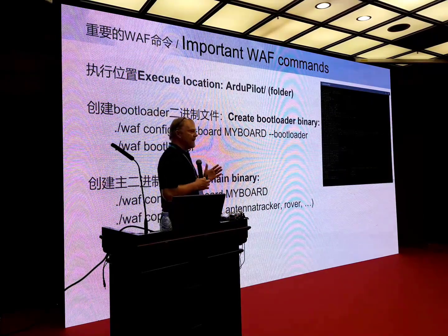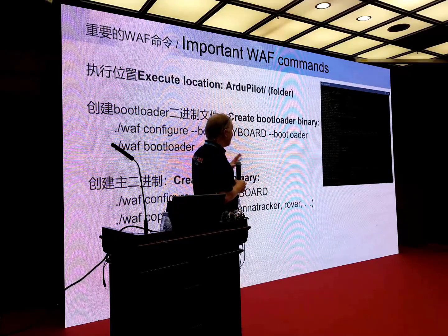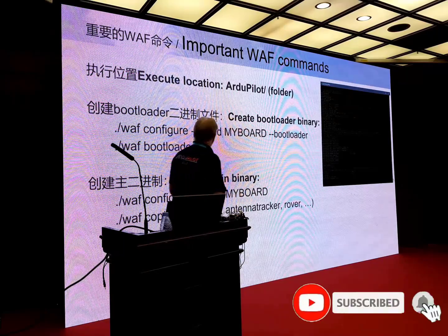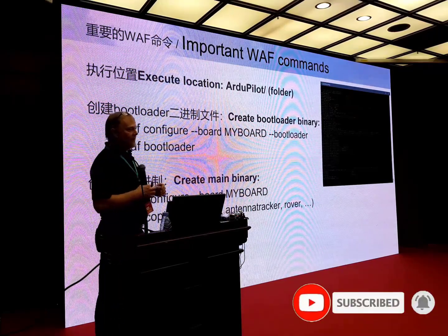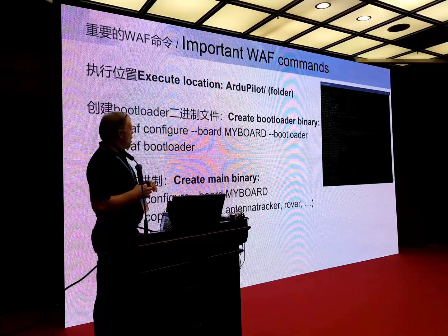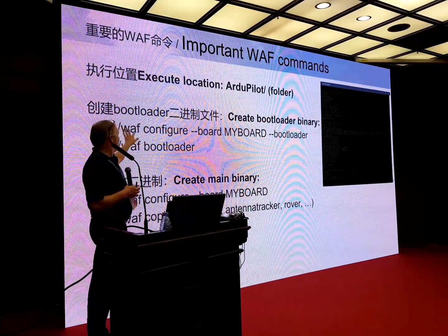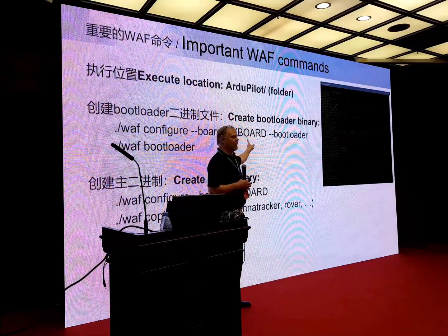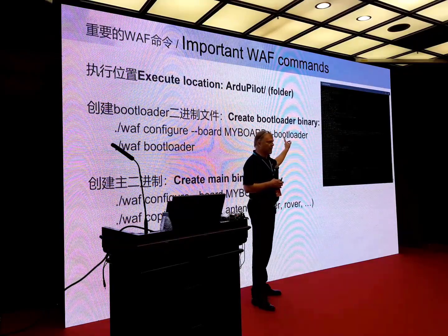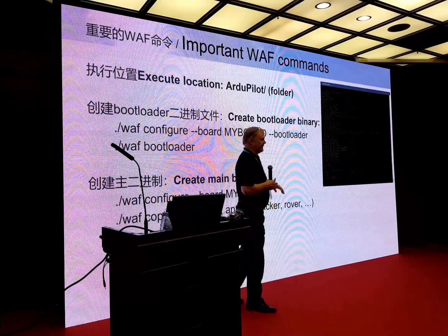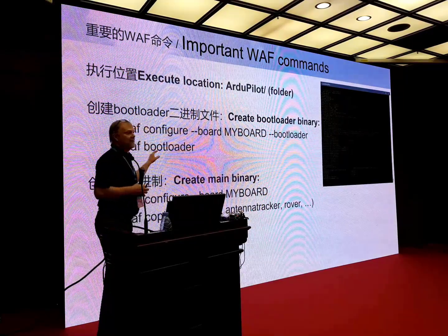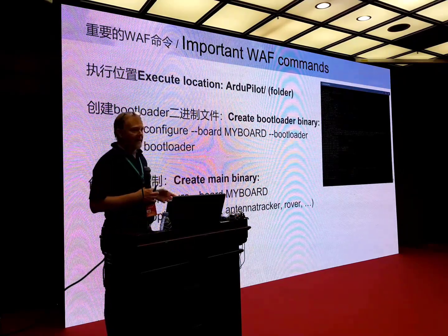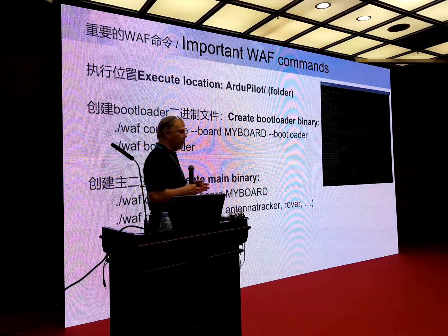When you're running the WAF build system, everything happens inside the main ArduPilot folder. Commands are, well, we tried to make it as easy as possible. Commands are really simple, straightforward. waf configure --board, what is my board name? And then if I want to build the bootloader, I just add --bootloader. After that, I say waf bootloader, build me the bootloader. And if all your configuration files are correct, in a matter of minutes, you will have a bootloader that works on your board.